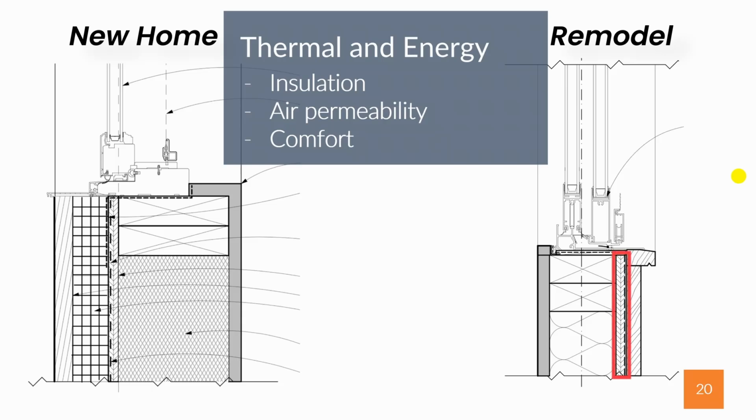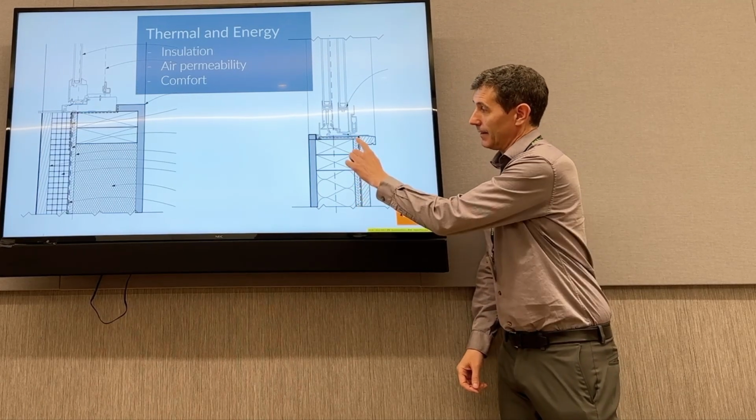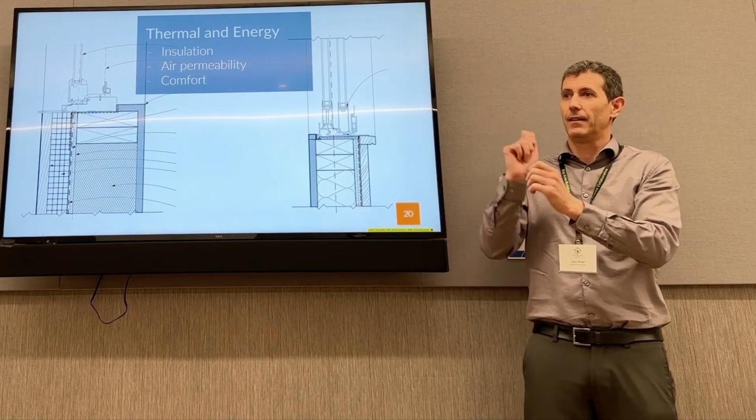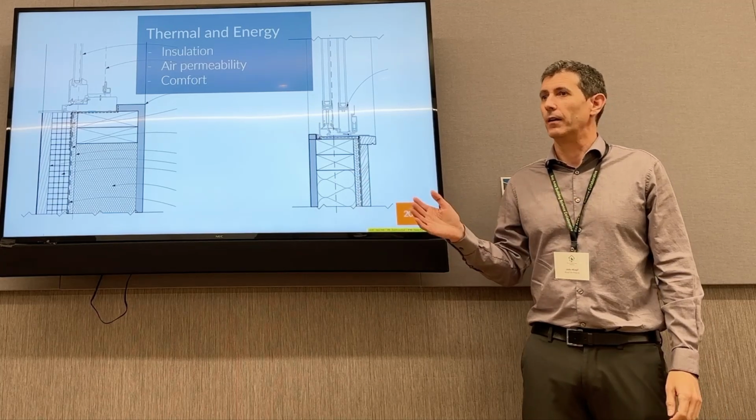This is only for the places where we removed the siding. We have plywood. Well, there's no plywood on the original wall. And when we remove the siding, we put this dashed line as the building wrap, right? So you can imagine for most remodel homes that were built prior to the 1980s, that isn't there. It's just wood siding nailed to studs, no air sealing whatsoever.